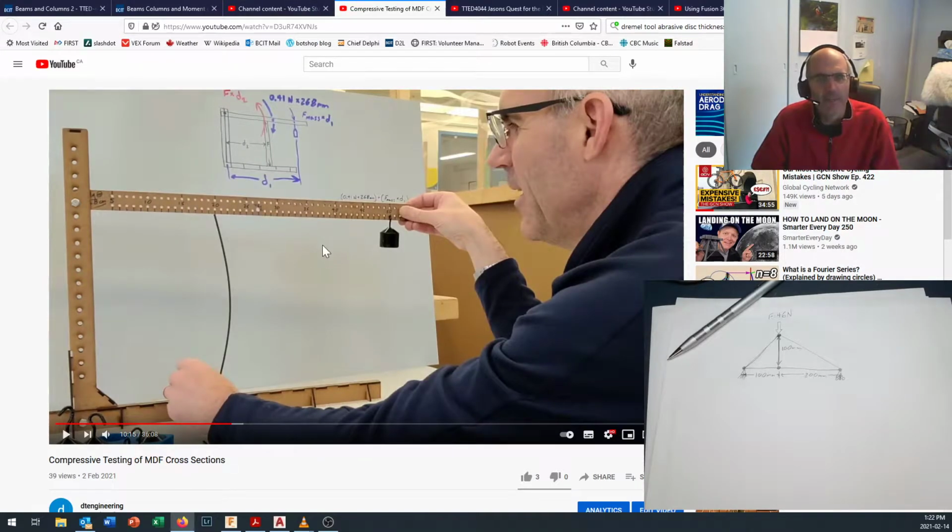And right here, you'll recall doing this test in the lab and look at the shape of that curve. That is a continuous smooth curve coming right up and down here. Now that is indicative of our load conditions, and that's what I'd intended for this truss loading. Our simplest type of compressive failure, our simplest buckling failure, is when you have a pin at each end, and that's free to rotate at the ends right here, and you can see that it's free to rotate because this is not being held in place.